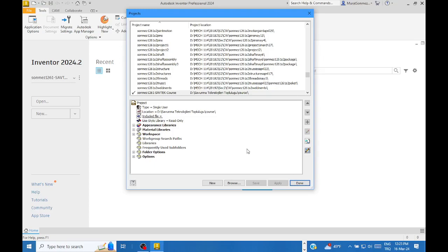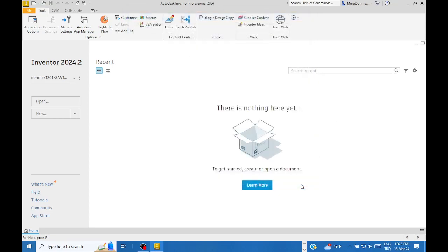If you need to open an existing file from the project folder, when you click on the Open a File button, Inventor automatically brings the content of the project folder without asking for the address, which can save time, of course. That is the other advantage. Okay, click on the Done button, and the project definition is okay. And then, as usual, since it is not an assembly, it is an easy case to create as a model, a rectangular prism.